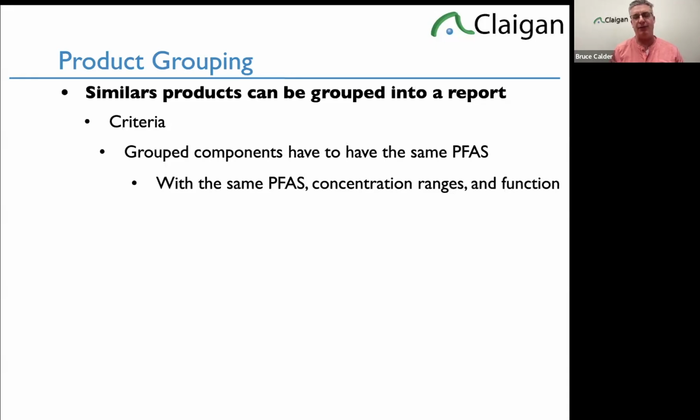Oh, so you can't use Teflon? FEP is Teflon. No, PTFE is Teflon. No, it's also Teflon. Another funny thing people have trouble with, and it even causes me problems when I'm talking about it: Teflon's a brand name. It's like Kleenex. PTFE is a Teflon, FEP is a Teflon. So when somebody says this is a Teflon wire, it's more likely to be FEP than PTFE. They're very similar, but they're actually different polymers.